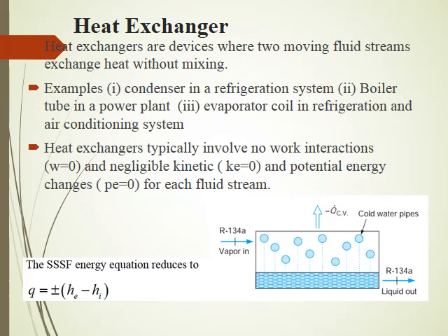So the steady state flow energy equation reduces basically to Q is equal to plus or minus He minus Hi, where He is the enthalpy of the stream that is leaving the control volume and Hi is the enthalpy of the substance that is entering the control volume.